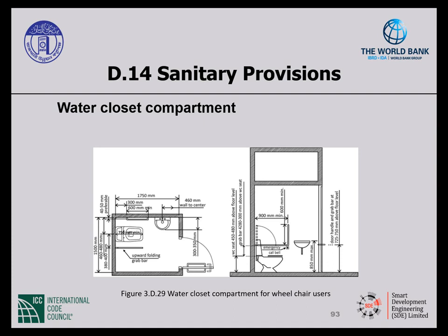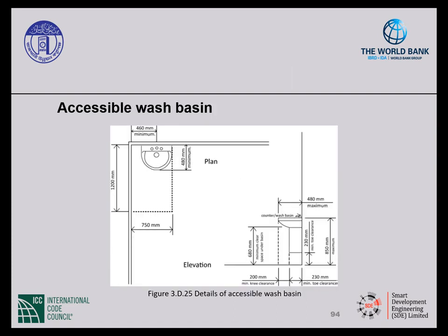And if part of a group of toilets, say a compartment inside a room, you should provide a minimum 1,200 millimeter wide path for the approach. We'll start with the fixtures within the washroom and the requirements for each one.